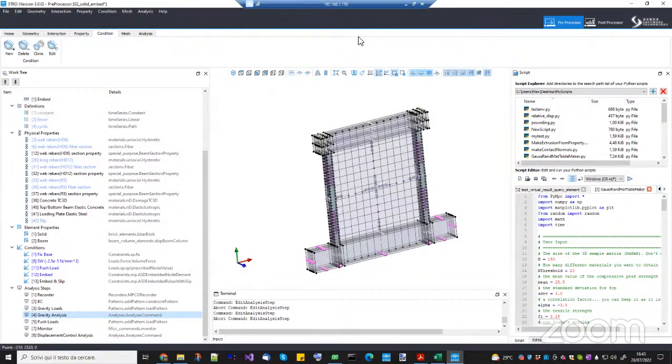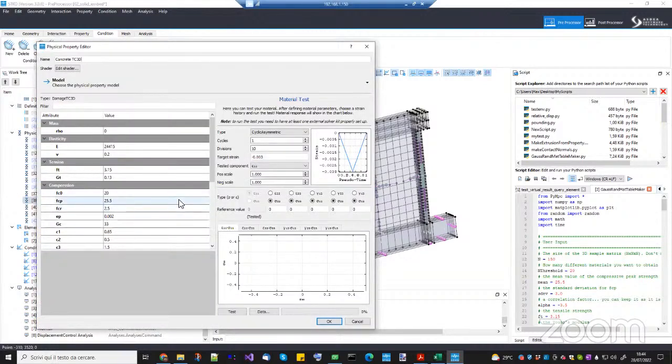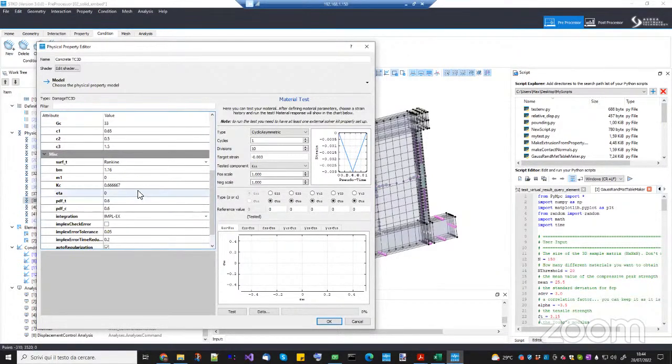Probably we have been talking about this one. As I told you, this is a simplified plasticity model, so you cannot actually specify the latency parameter directly, but the number that you put here, and it is also explained in my paper about micromodeling, basically governs the latency if you are under shear stresses. A value of 1 is basically the minimum amount of latency that this model can show. A value of 0 shows the maximum latency.